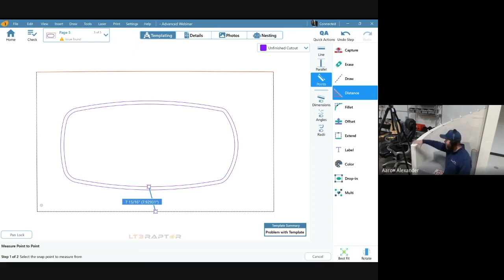If you're doing a cap for this, though, that cap better be a consistent, perfectly symmetrical radius. Okay, so even if I'm going to install a countertop down here and then cap that, we can still do our scribe in continuous and shoot 31 points across this thing. Then I go in the software and I draw an arc off of just 3 points.